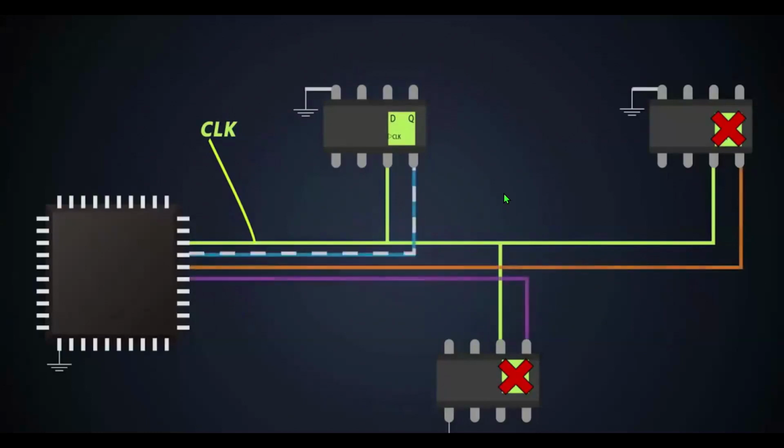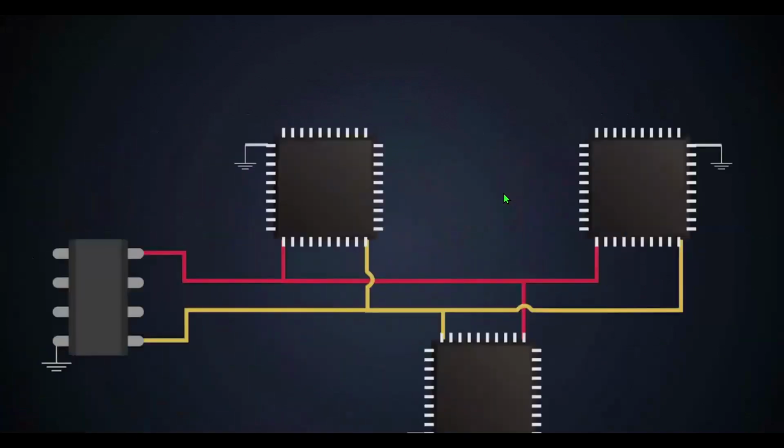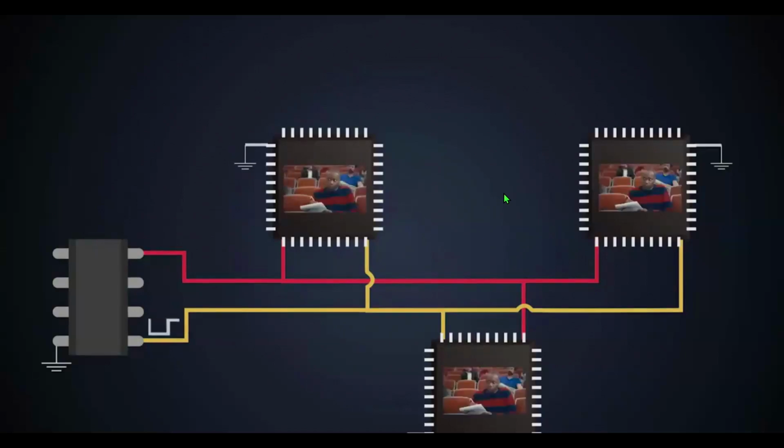In SPI communications, we can enable a communication device with chip select, which puts the other devices in sleep mode or power saving mode. Whereas in I2C, even though the data packet is not intended for all slaves, all of them need to be awake and allow the clock signal to pass. Each slave in I2C continuously validates whether the data packet is meant for it by comparing the addresses transmitted on the bus. This phenomenon consumes power dynamically.